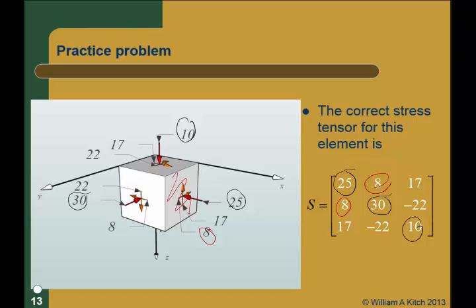It's a negative plane, so we're in negative land. It's pointed in a negative direction, so it has a positive magnitude. Why is it a negative plane? It's a negative plane because this normal stress is a positive 25. It's positive, it's compression, but it's acting in the negative xyz direction, right? It's confusing. Don't get me wrong. Everybody sits there and nods their head until they try and do this, and so it's confusing.